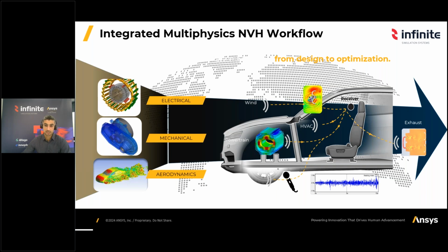There have been significant improvements in terms of NVH, so noise, vibration, and harshness simulations in the last, let's say, 2 to 3 years. And it's very nice to see that now with 25R1, there is really a complete solution, a complete workflow that is robust, that allows users to combine different aspects of the NVH, like electrical, mechanical, aero, for overall powertrain design, acoustic comfort inside the cabin, for example, taking into account the different sources of noise and vibrations, overall minimizing the vibrations, etc.